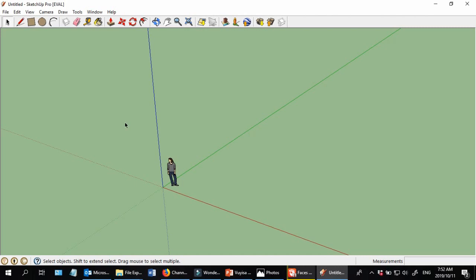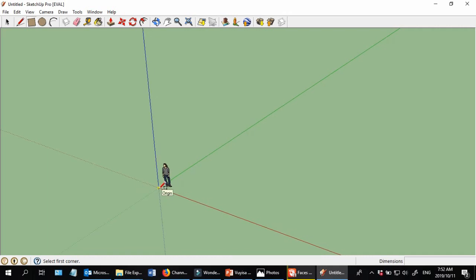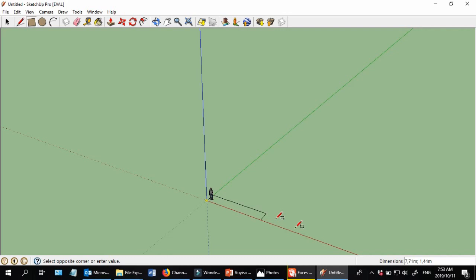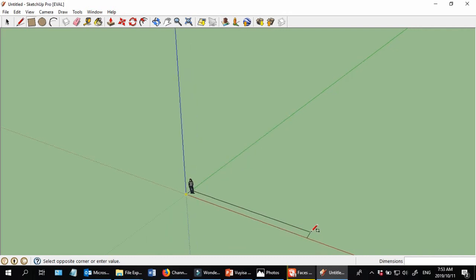Alright, so let's get started. The first thing I'll do is I'll draw a rectangle. Okay, so I'm going to use a shortcut, and the shortcut for rectangle is R. So there we go. And what I want you to notice here, okay, is that as I draw, the dimensions of the shape that I'm drawing appear here on the bottom right of the screen. So let's try that again. Okay, so I'm pulling it this way, and I can actually enter numbers on my keyboard. I can enter the numbers of the dimensions that I want. So for starters, let's enter 80.